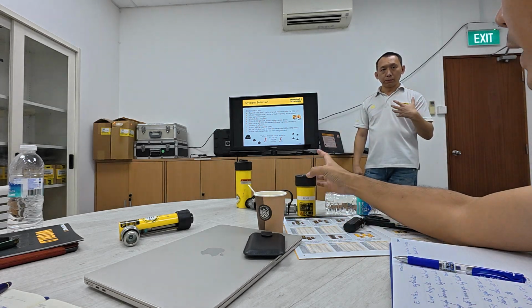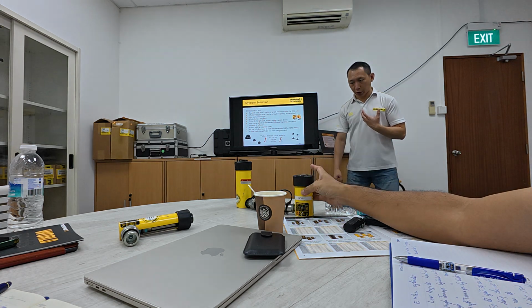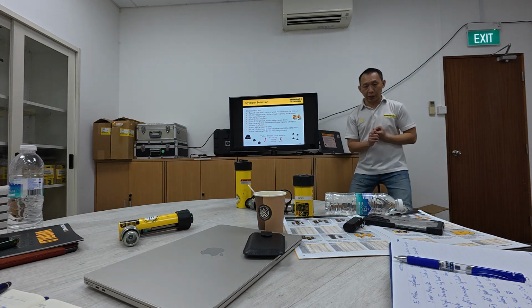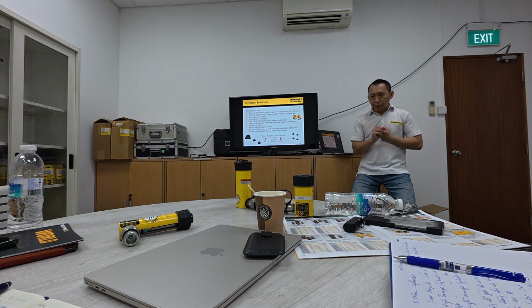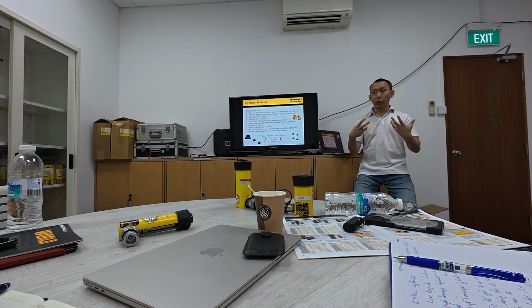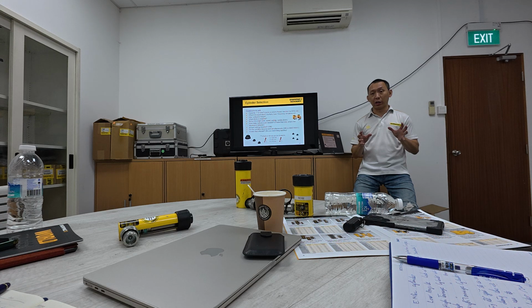How can we know when the cylinders cannot withstand the load anymore? One thing, when we talk of frequency, you have to ask the customer what these applications are for. If they tell you it's production mode, high cycle, manufacturing, 1 hour run 10 times up, 20 times up and down again, then probably you have to rethink whether they are talking about the right type of cylinder.